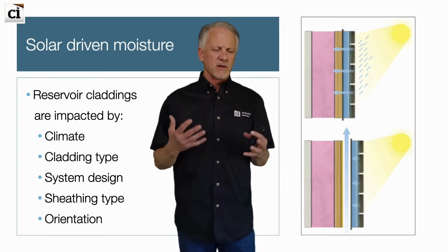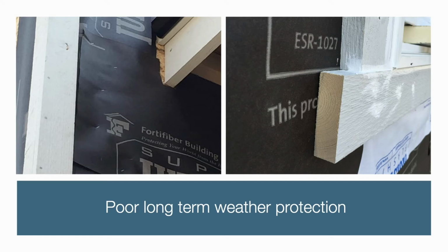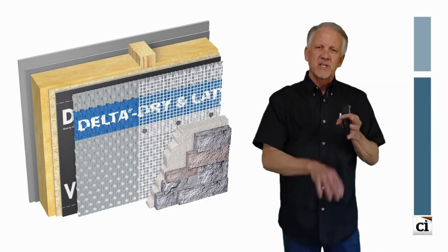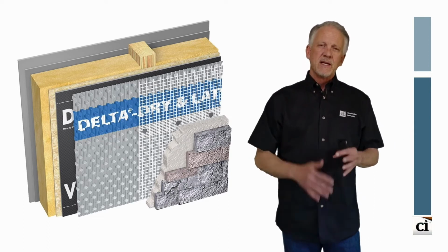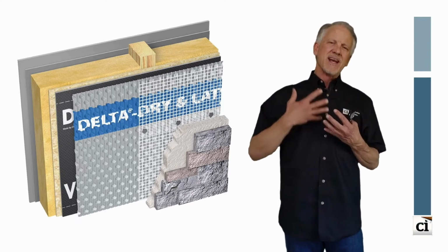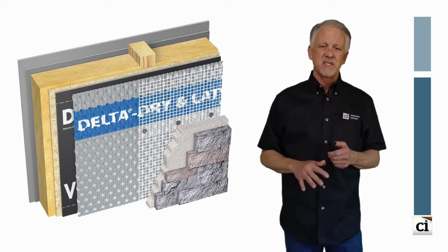Finally, when we look at products, we look at types of building papers, weather-resistant barriers. Some weather-resistant barriers have different performance characteristics, and sheathings have different performance characteristics. As we look at the way in which water affects our buildings, we've got to make sure that we're flashing everything away from these claddings, making sure that we're doing a careful job of installing our cladding systems, especially things like stucco and stone and brick, to make sure that if water is going to be in those areas, it finds a place to quickly drain away so that it can be removed and not stay within the assembly, so that the material itself will hold some moisture, but we don't add extra liquid water to store and stay in the system for too long.